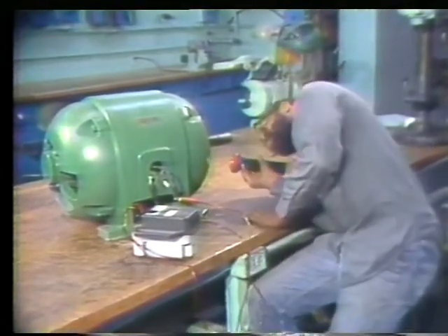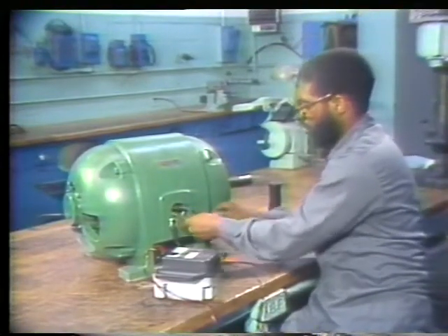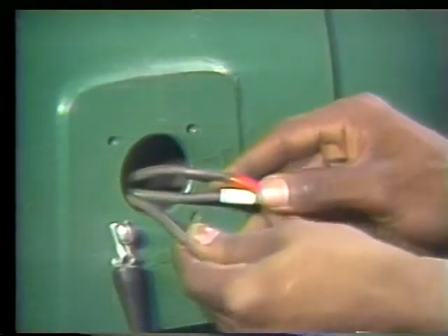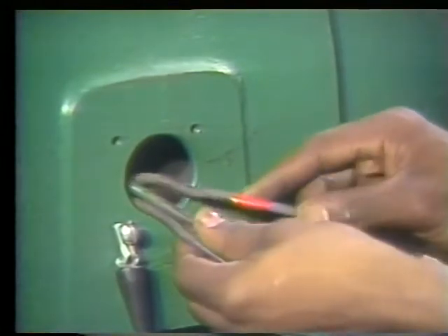So look for any signs of moisture. Moisture is a common cause of grounds. If you do notice moisture, you may be able to solve the problem by drying the motor. This might be done by using heat lamps or by blowing hot air through the motor. But there are lots of ways of drying a motor. Now, if there's any question in your mind, ask your supervisor what procedure is used in your plant. Check to see if there's any chafing of the leads on the stator coils. If the ground's caused by chafing of the leads, you probably can re-insulate them, and that'll take care of the problem.